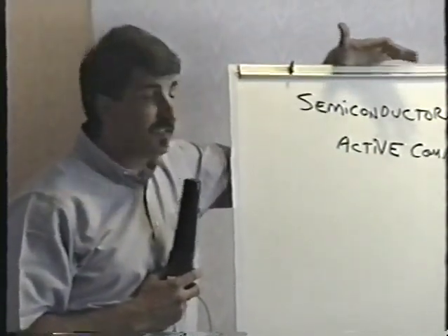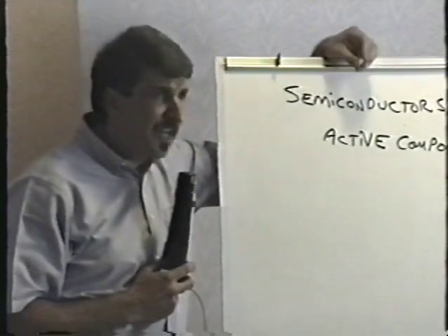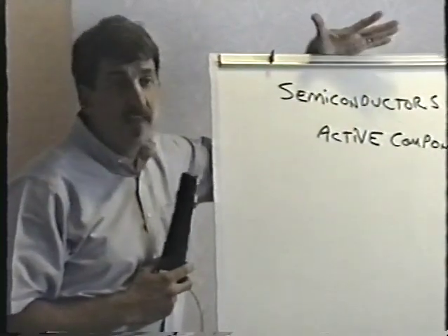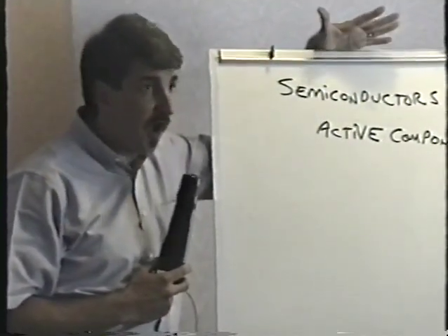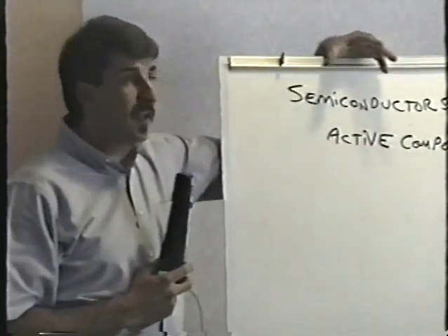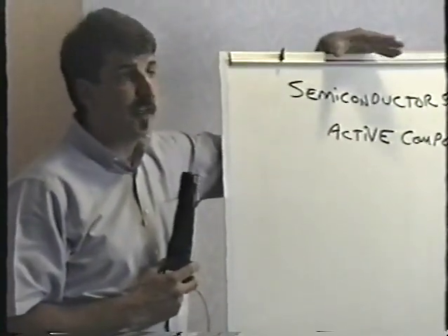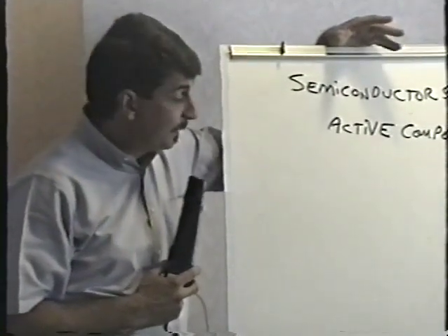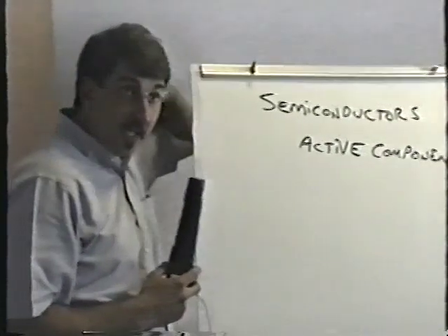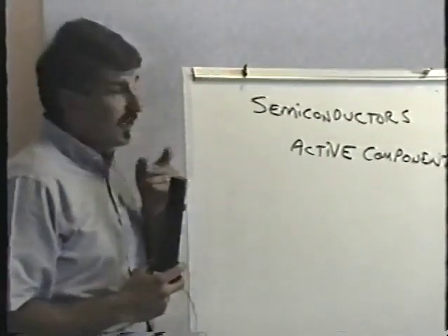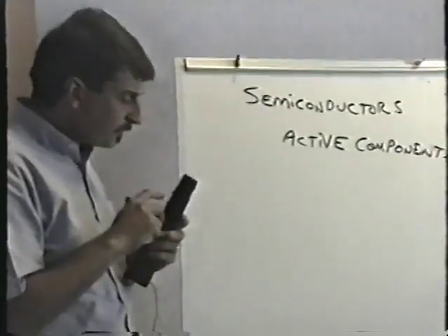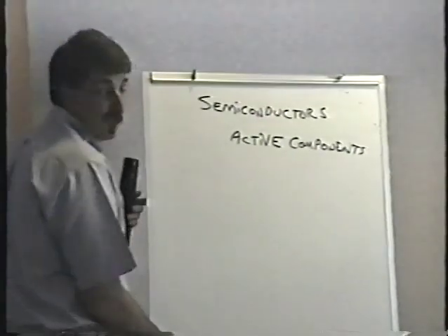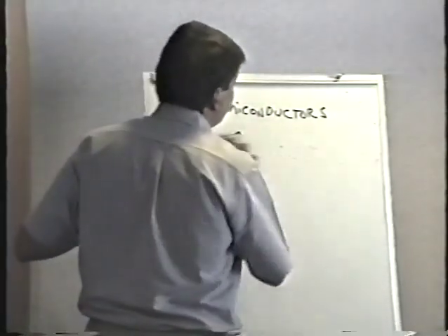And as a result, since semiconductors are the things that are actively switching on and off in a circuit, they fail fairly often. Other than capacitor failures, diodes and transistors are really the most common types of failures that we have. Again, capacitor failures happen because the electrolyte dries out, but semiconductors fail because they are working very hard, switching on and off, controlling the flow of electric current.